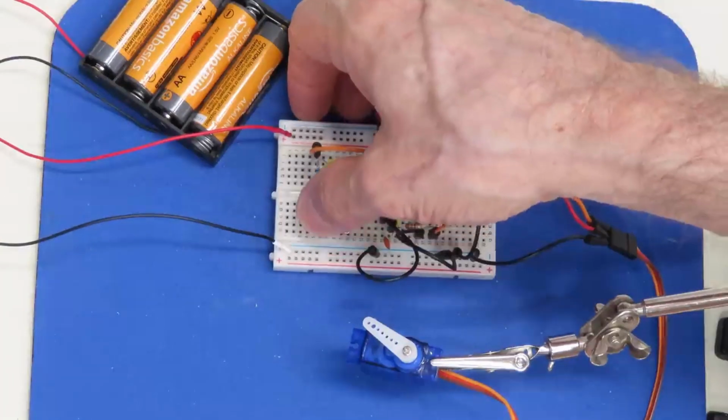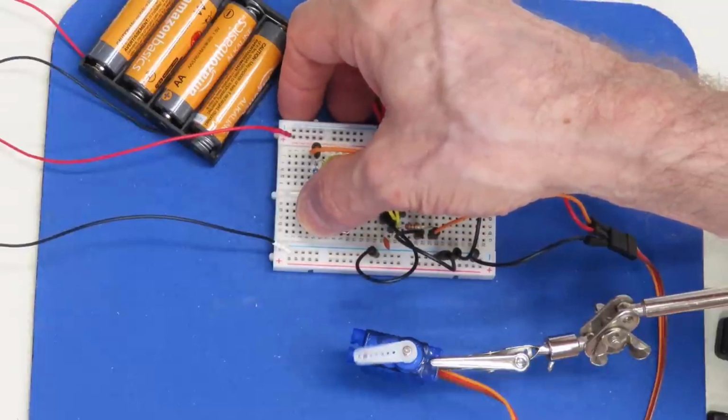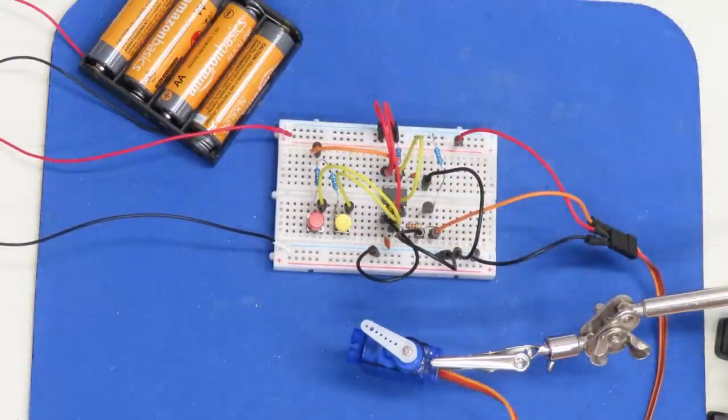And so it does have an advantage over that kind of a system. And you could use something like this to actually drive a servo motor, not just test a servo motor, but of course you would need to experiment a bit with the value of resistors that were attached to the switch or whatever it was that you were using in order to drive the motor. But again, another great use for a 555 timer.